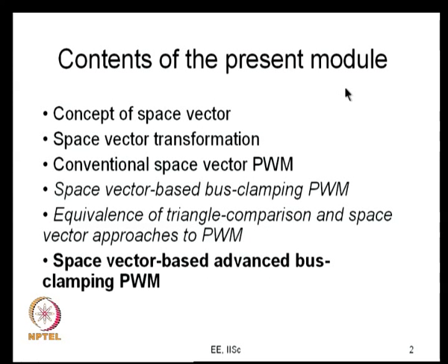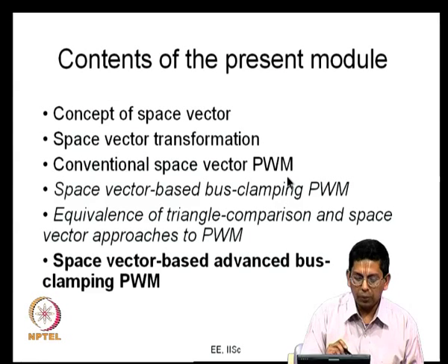The present module has been focusing on space vector based pulse width modulation. We earlier covered the concept of space vector, what exactly you mean by a space vector, and we did space vector transformation, how you can transform 3-phase voltages or currents into the space vector domain. Then we dealt with conventional space vector pulse width modulation, which is a very popular method, quite similar to sine triangle PWM.